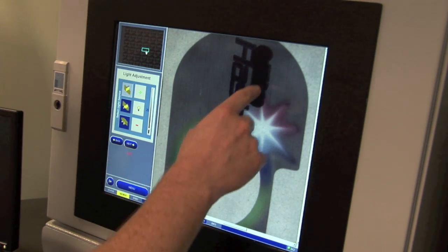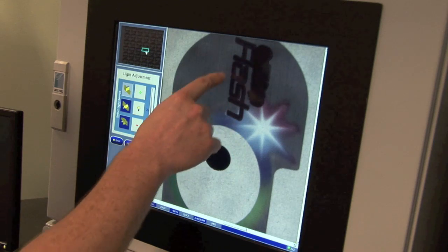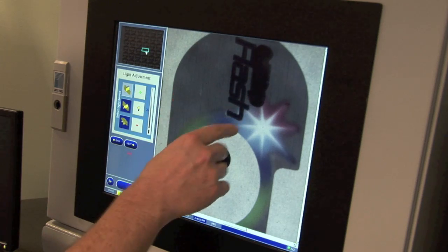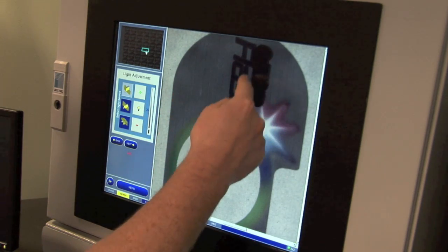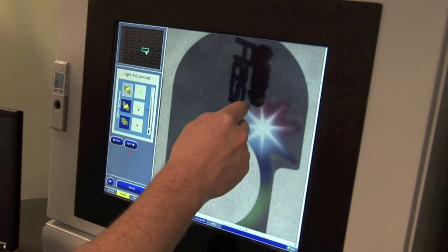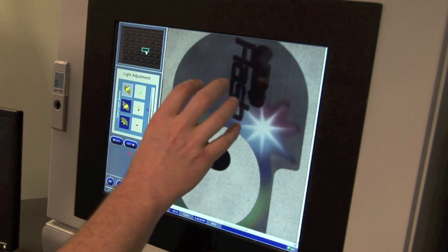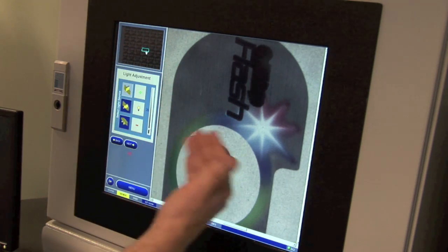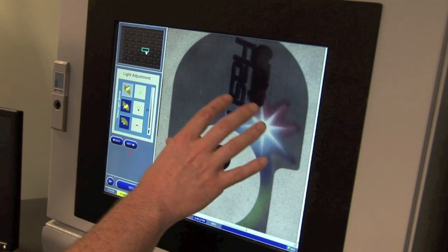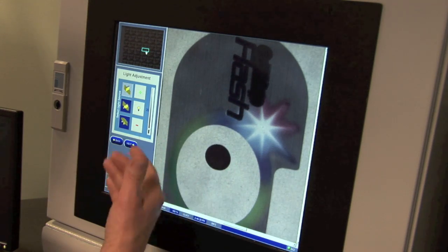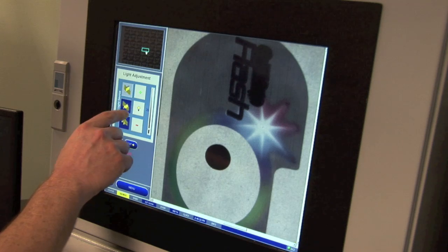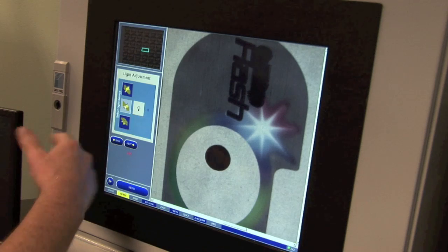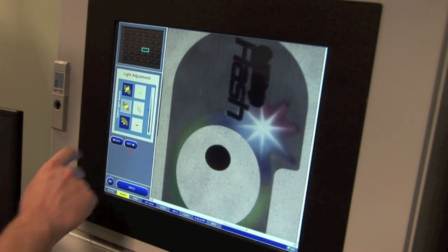But also you'll notice that the text in this area, while you can see the outline and it appears that we've got an A, an S, and an H, it's very difficult to see what's actually happening in this area. And we can also see a very, very dark area here, which also has text. But because all of this area is a mirrored, very, very shiny surface, our top light is being reflected away from this area and is showing very, very dark. So to solve that problem, we have a second light which can also be adjusted, which is called our foil light. So over here, we need to switch from our top light to our foil light. And our foil light is currently at 0, so it's effectively off. So we want to turn that on.